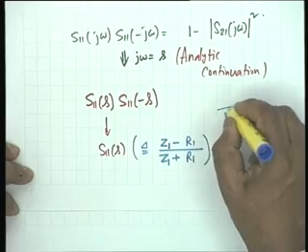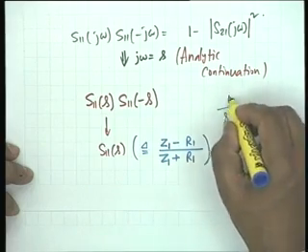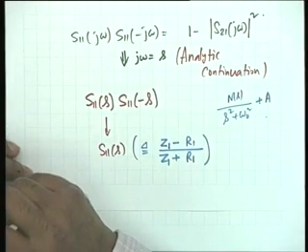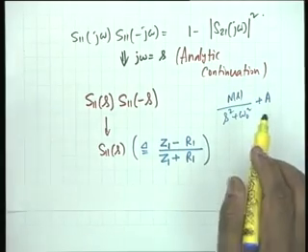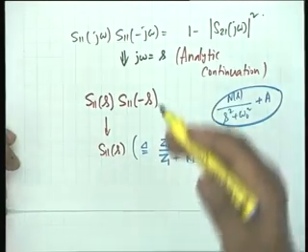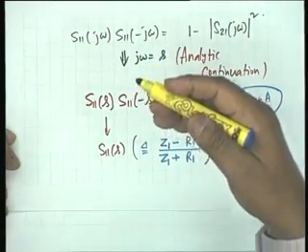Suppose I have a function like this, s squared plus omega naught squared. You add a resistance A. Adding won't change the poles. You are quite right. Do you see that his claim is correct? If you add a resistance, the poles would not change, the zeros would change. Okay. Therefore, the poles of Z1 plus R1 are the same as the poles of Z1, but its zeros will change. Zeros of Z1 plus R1 shall change.